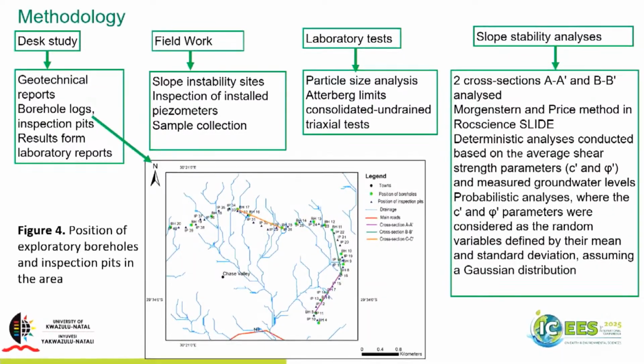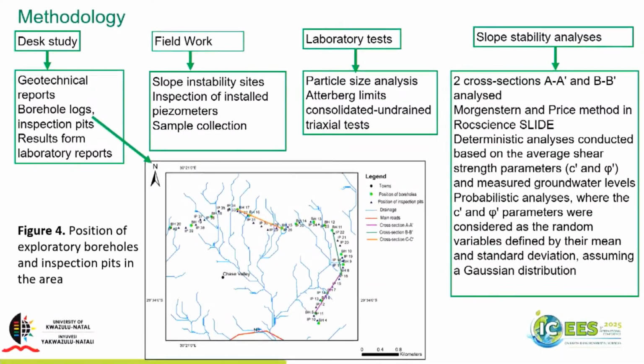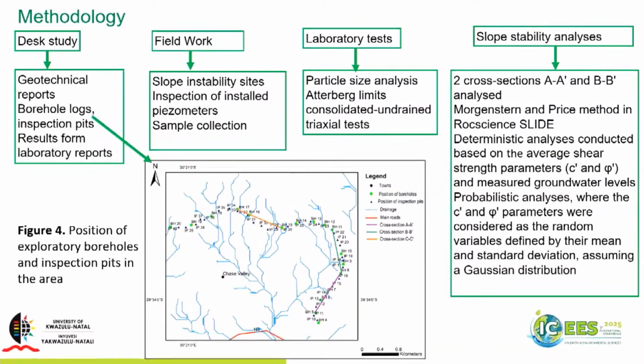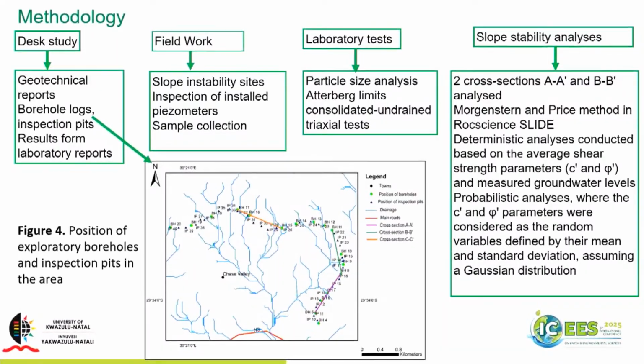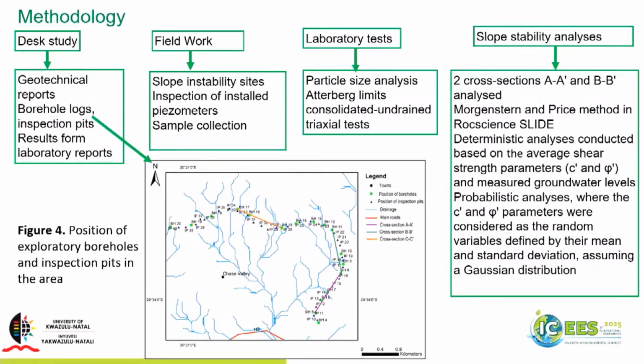And the laboratory tests include particle size analysis. We looked at the index properties, mostly the Atterberg limits, and we carried out some consolidated undrained triaxial tests. And we selected two critical cross-sections for the slope stability analysis, using the Morgenstern and Price method in the RocScience software Slide.